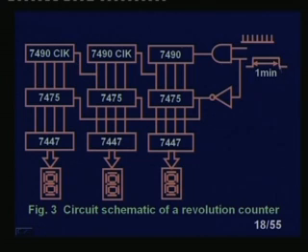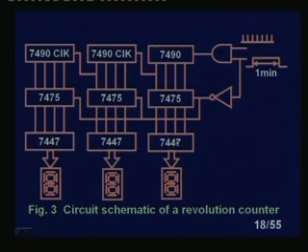So, when this falls, this will activate it because this will be 1. Whatever data we have at the output of the 7490 in the 4-bit, that will come to the 7475. Previously it will latch to the previous values. Then it will come to the display, and it will do BCD to 7 segment decoding, and it is in the 7 segment display, right. This way it will work.